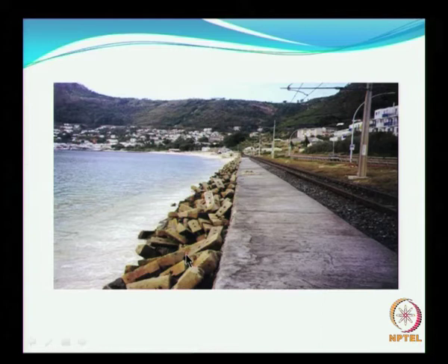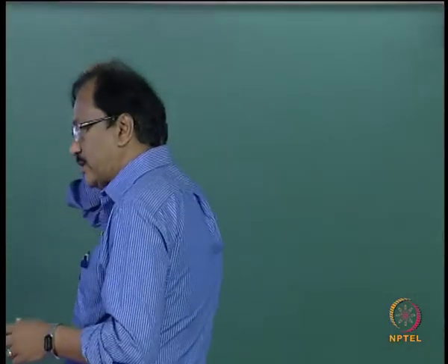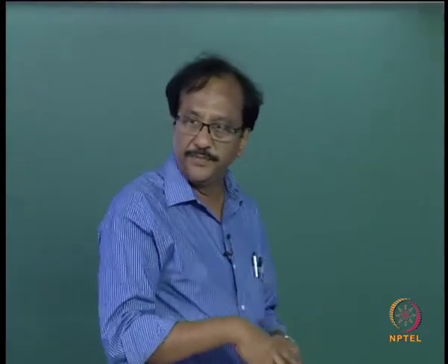Now this is acting as a buffer, and it does not create any problem, and it is acting as a protection measure, okay. So sometimes such a situation can arise, wherein you try to use material which is not needed as a protection measure. I will show you later as an example where such a situation took place, wherein we did not want the concrete pipes, we removed the concrete pipes, and they have been used as a protection measure for preventing erosion along our Chennai coast.